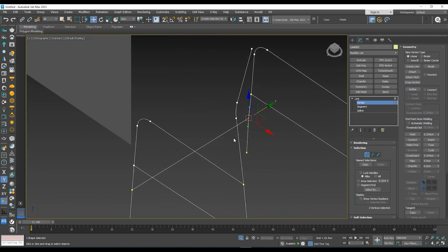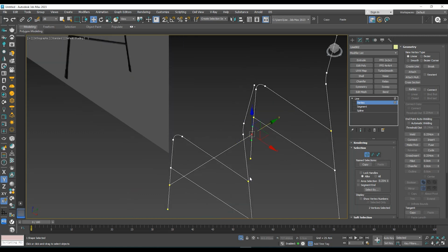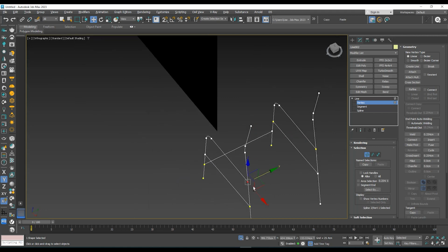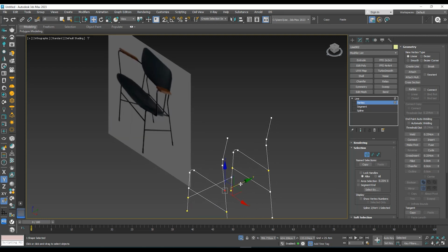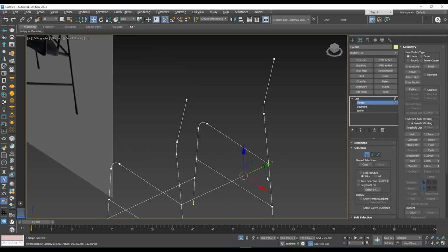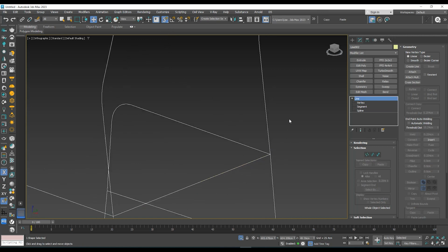No need to make a refine because there is already an existing vertex over here. So we make an extension by selecting this vertex, hold shift and adjust over here, attach. So now I can go for 3, okay, like this, done.